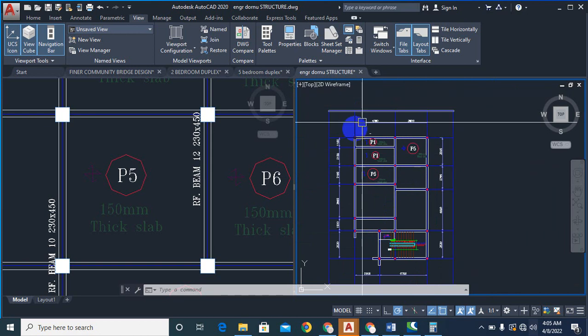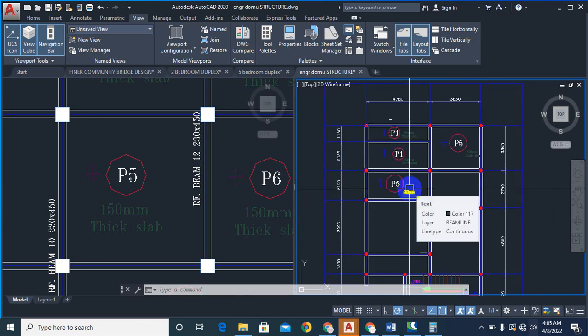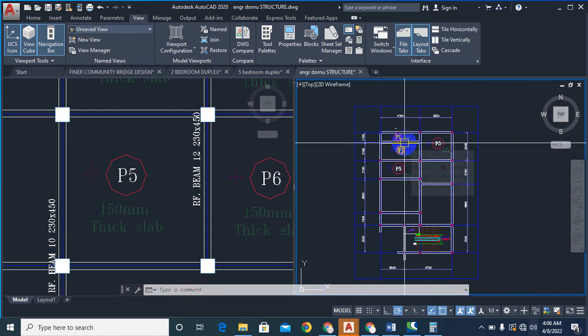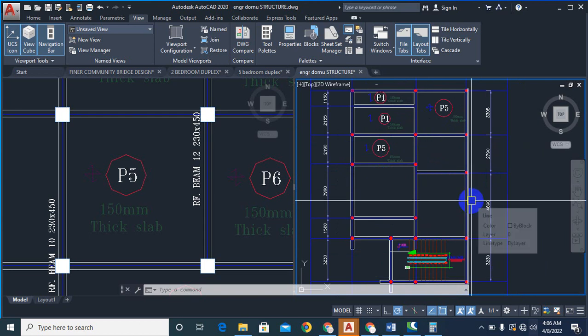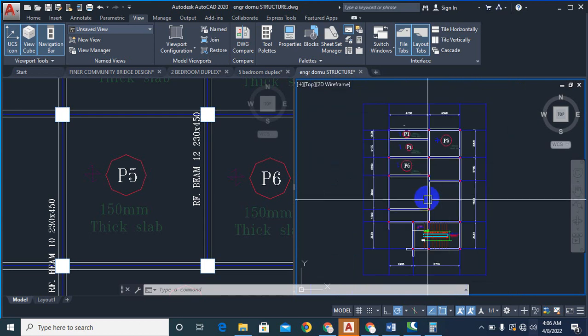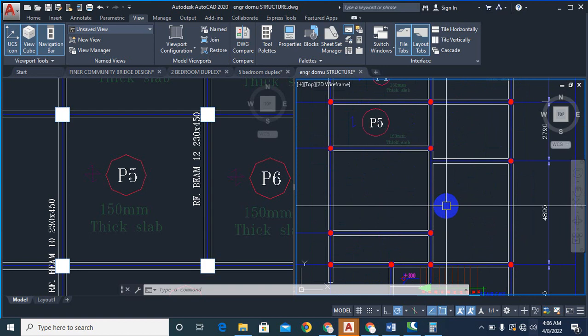By the time I run this design, using either manual or a software, it is going to tell me the structural members that have failed and the structural members that have passed. In a case where a structural member failed, I may need to change the depth of that particular member, or increase its thickness. For example, if your beam failed, from years of experience, I can tell you that everything here will pass. But there are cases whereby you run your design and a member will fail. By the time your member fails, you will need to change that structural member.